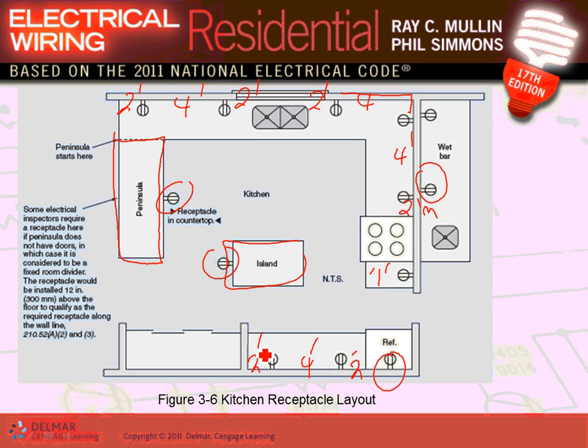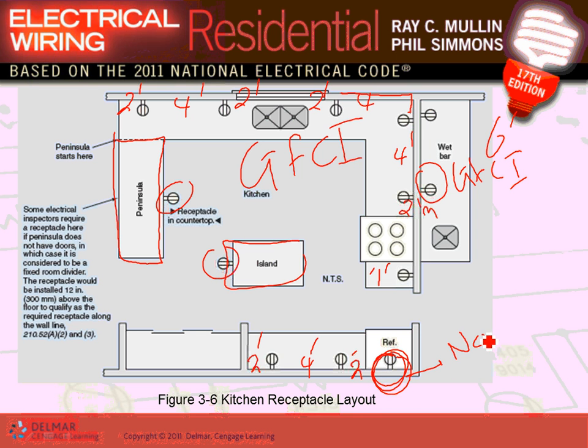Any questions, guys, about the 2x4? Does everybody know why the 2x4 is a big deal? Can I give you guys one little thing? In the kitchen, all these receptacles have to be what? GFCI, as well as if you are within 6 feet of a sink, GFCI. The only exception for the GFCI is what? If you have a kitchen with one dedicated receptacle for the fridge, or non-dedicated, you don't have to have a GFCI. Any comments, guys?